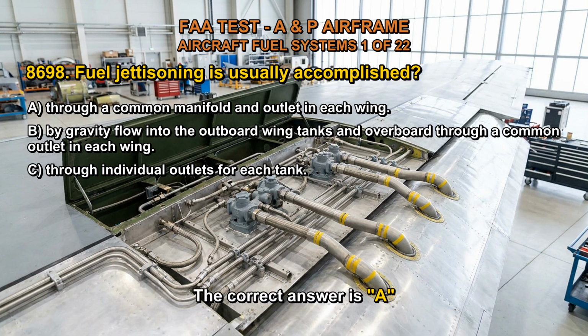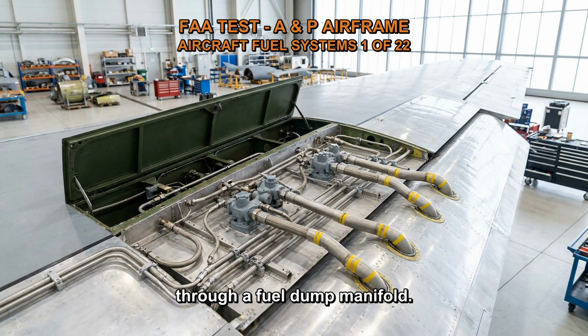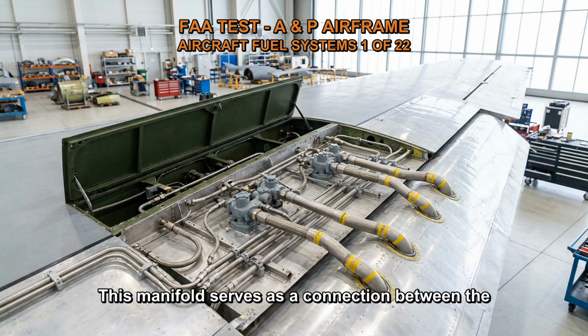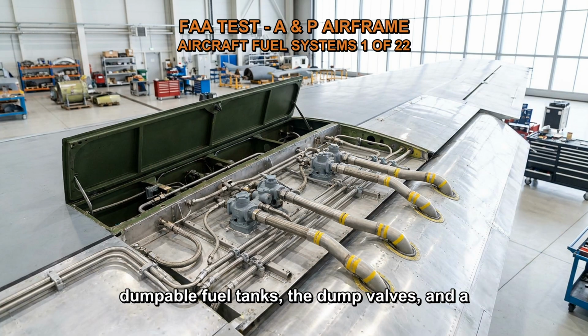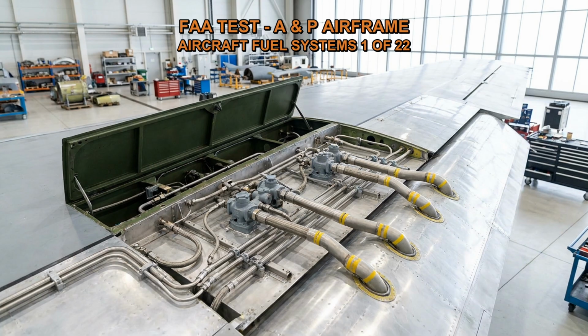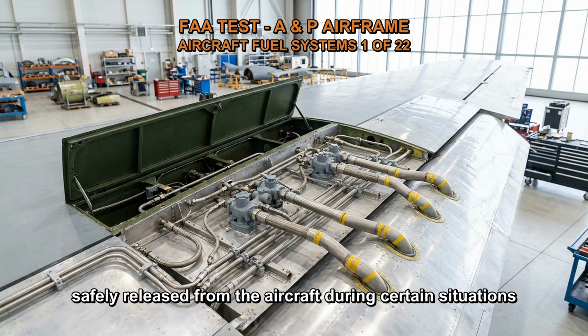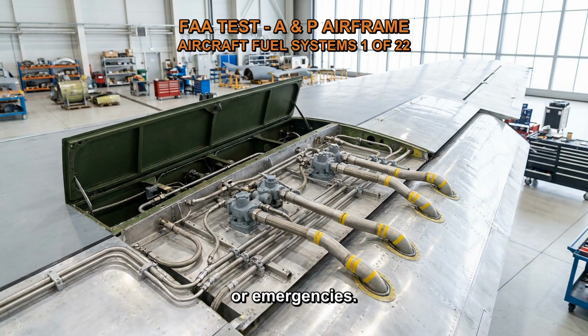The correct answer is A. The process of fuel jettisoning is typically facilitated through a fuel dump manifold. This manifold serves as a connection between the dumpable fuel tanks, the dump valves, and a fixed or extendable dump chute located in each wing. By utilizing this system, excess fuel can be safely released from the aircraft during certain situations or emergencies.